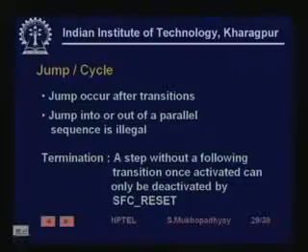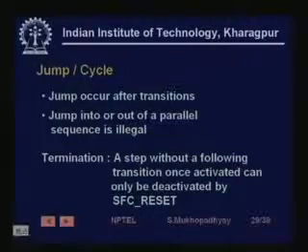Similarly, last, you may have termination of a program. So, a step without a following transition. If you have a step out of which there is no transition, then it is a dead state, and once it is activated, it can only be deactivated by a special instruction called SFC reset.